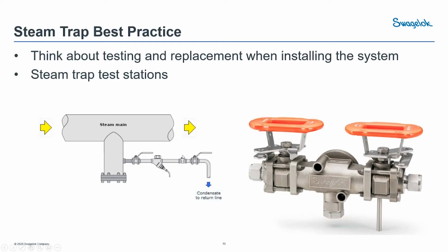And they also have here this component, which is hard to see what it is, but that's actually a sight glass. So what that allows you to do is look inside here through a window and see, is there condensate flowing through here periodically? Now, sight glasses aren't always great. They tend to plug up, or they tend to haze up over time and be hard to see through, depending on the application.